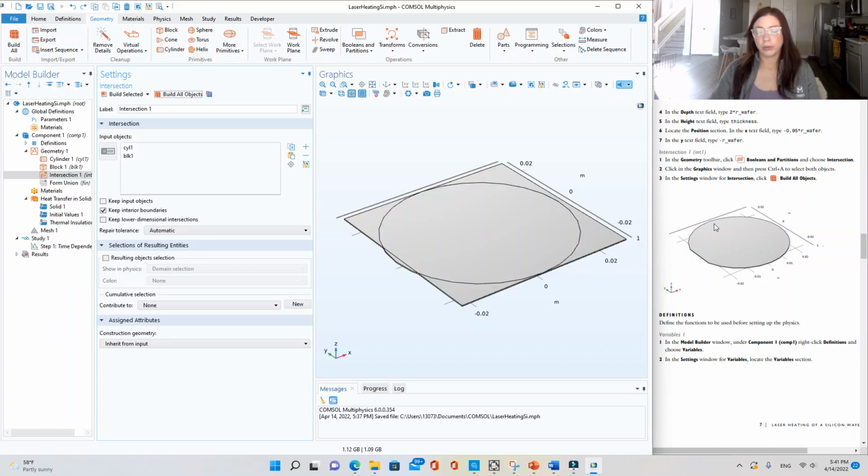we want the shape to be like this because that's how a silicon wafer in the fab will have a flat end. You'll call this the crown and this the flat. The wafers are created by first making a silicon ingot or boule: you seed a crystal and then grow an ingot.